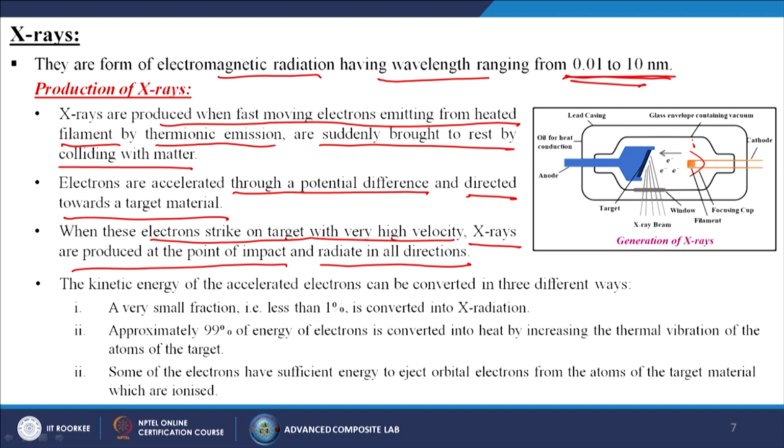Automatically the electrons move from the cathode to the anode side and hit the specimen. When they hit the specimen, X-rays are generated, and the X-rays penetrate into the substance, and after transmitting they fall upon the film and generate the image itself after developing the film.